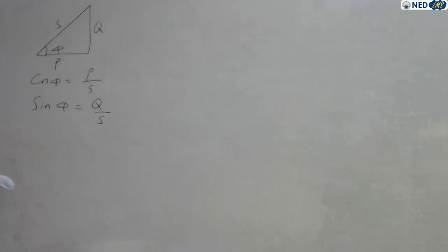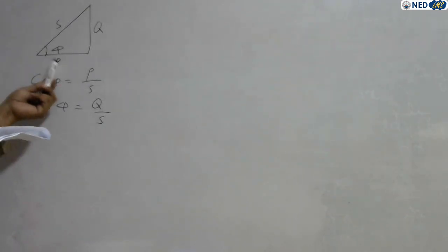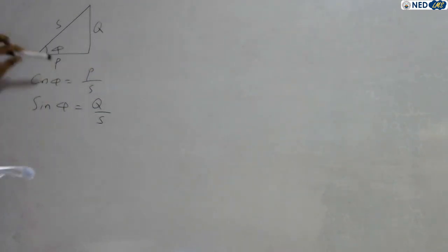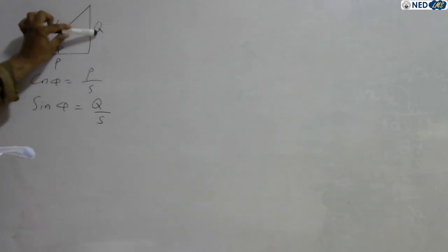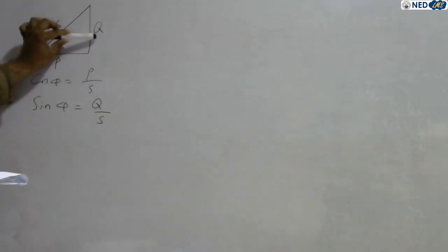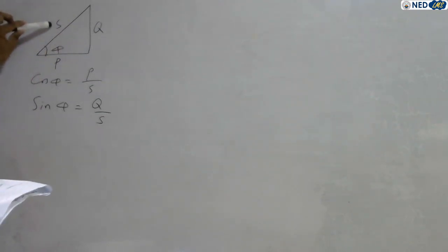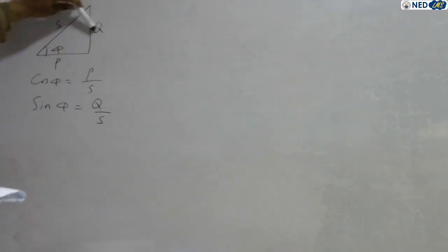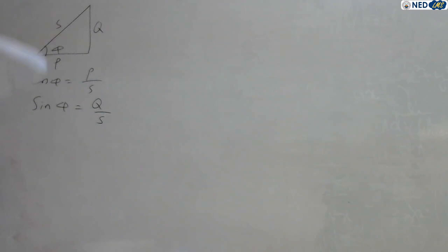So just remember this basic triangle. This one is the base, this one is the hypotenuse, this one is active power, this one is reactive power, this is apparent power. The units are kilowatt, kilovolt ampere reactive, and volt amperes. This power is supplied by the source, and these two powers are absorbed by the loads, because load takes active power as well as reactive power.